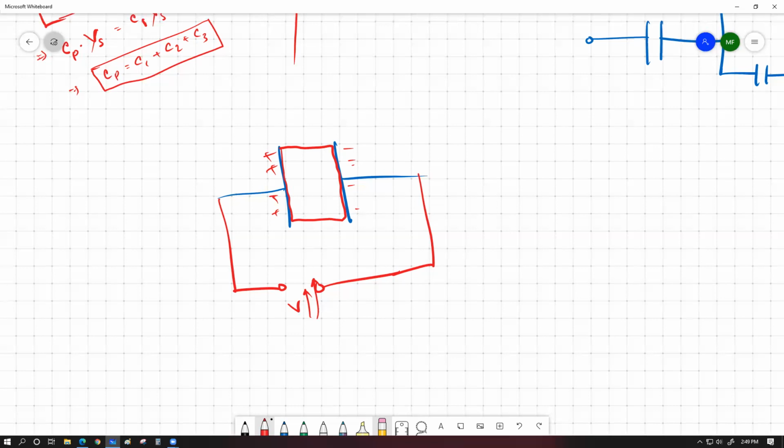So what it means is that if we start to increase the voltage across the two plates of the capacitor, there will come a certain point at which electrons are going to actually jump or spark through this material, no matter how good an insulator this is, even if this is vacuum, it doesn't matter. There is definitely a certain voltage value for whatever medium you choose, or even if you choose no medium at all, at which the electrons are going to start to discharge through this medium, and electricity is going to start to go through the bulk plate. This is the point where the capacitor no longer can be charged to a higher voltage. This is the limiting voltage of the capacitor, the maximum to which it can be charged.